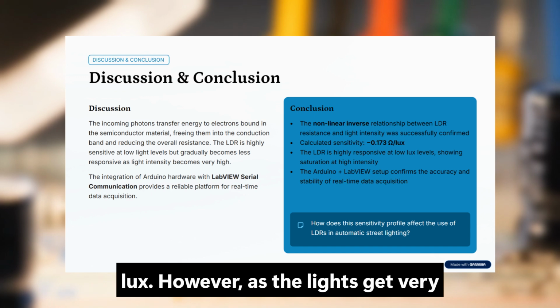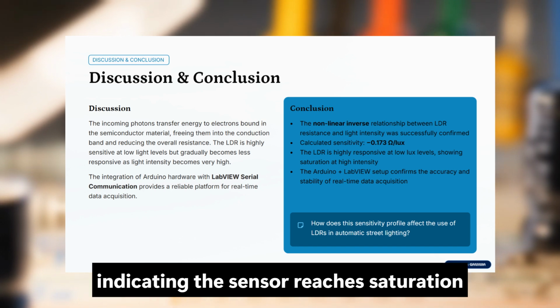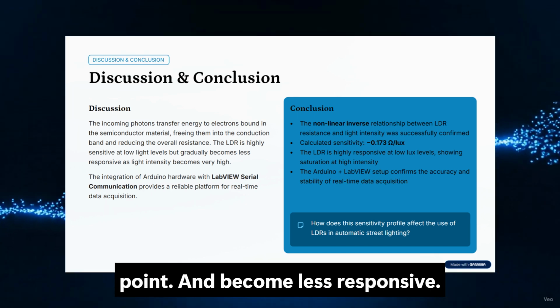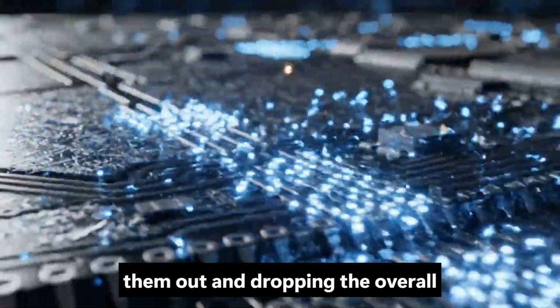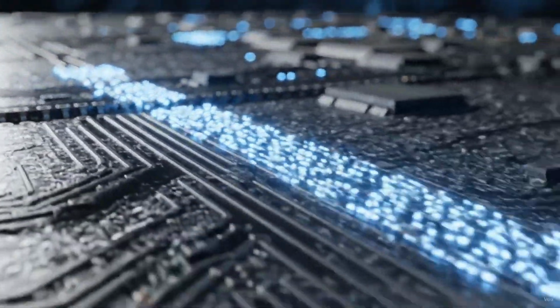However, as the lights get very bright, the curve flattens out, indicating the sensor reaches a saturation point and becomes less responsive. Physics explains this perfectly. Incoming light photons transfer energy to electrons in the semiconductor, freeing them up and dropping the overall resistance.